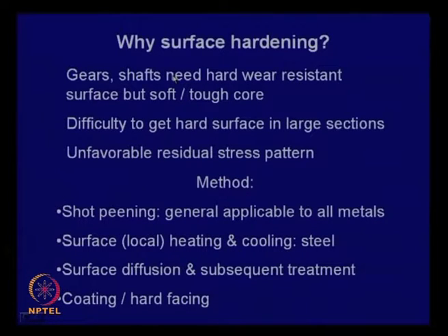The diameter itself may be half a meter, and the length may be quite long, maybe 10-15 meters, and it rotates. Many of these components rotate at very high speed. Therefore, the surface is highly stressed, and the steam also passes through it. It is also supposed to have good wear resistance.